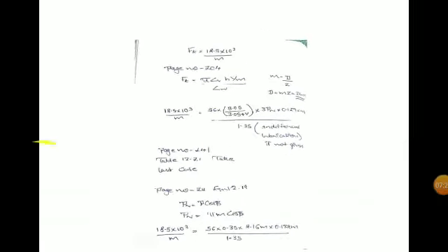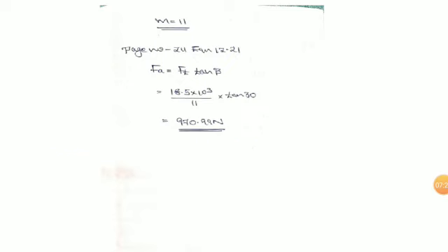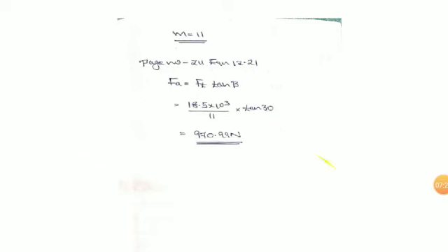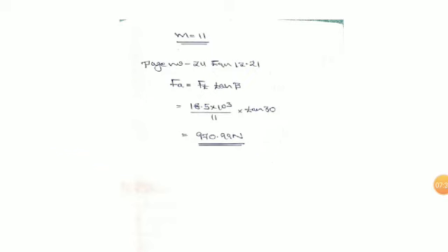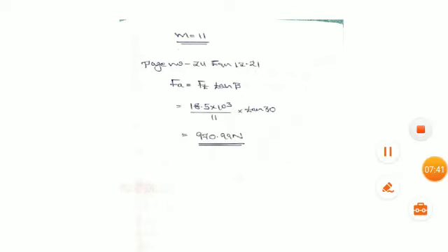Finally you will get the value of m as 11. And one more thing asked in the question is FA, that is the axial thrust, which is FT tan beta. FT we already found out. So upon substituting FT, we can find FA as 917.99 Newton. So this is about the problem which is discussing the design of helical gear. Thank you.